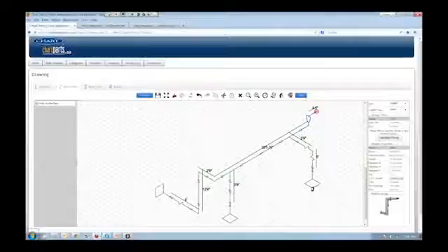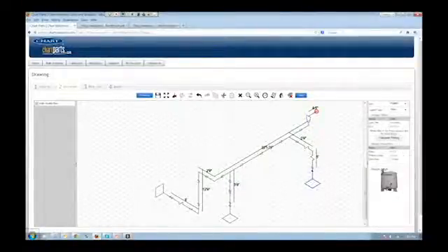Well, I have to highlight each application point. Here's application point number 1, and it's O2 service. I have a pressure drop of 2.62 psi and a flow rate of 1.5 GPM. I come back to this one, click on that, and it gives a pressure drop of 3 psi and a flow rate of 1.